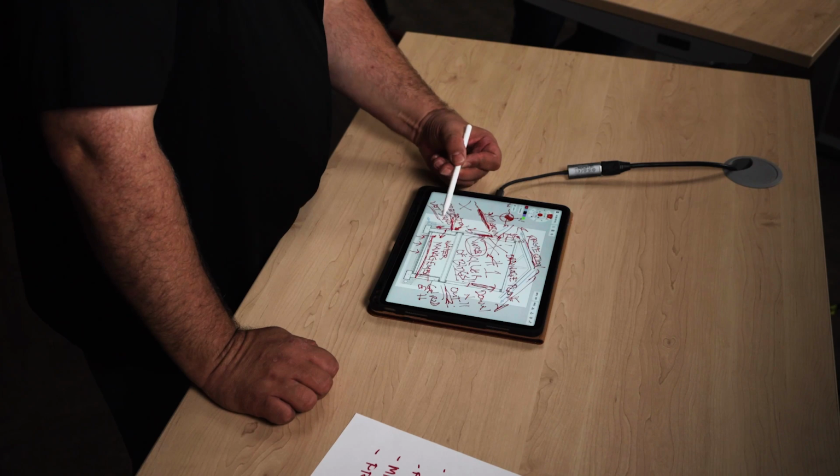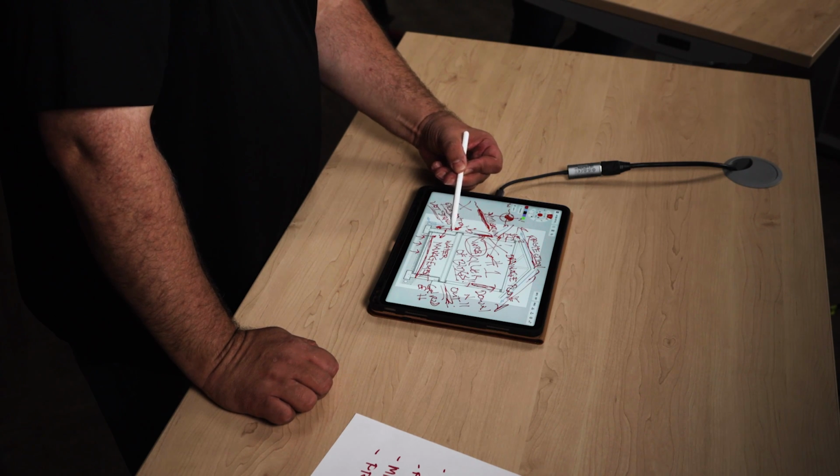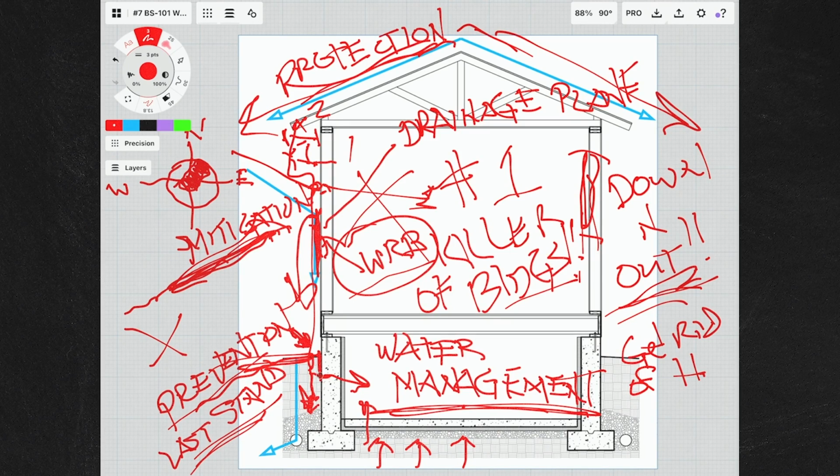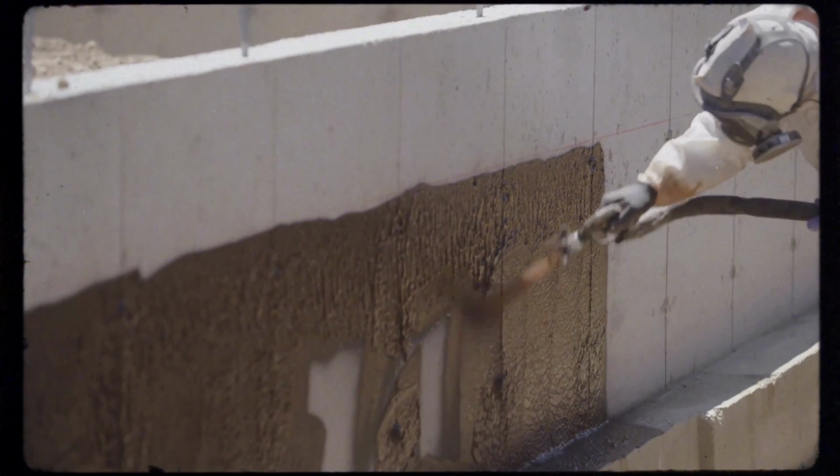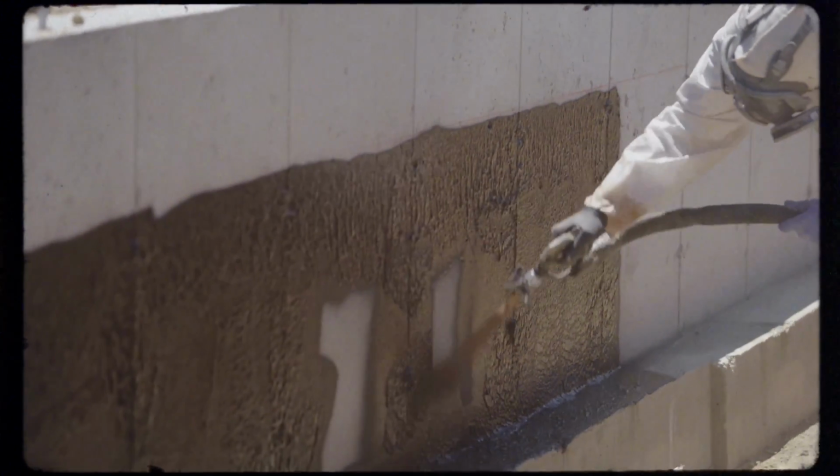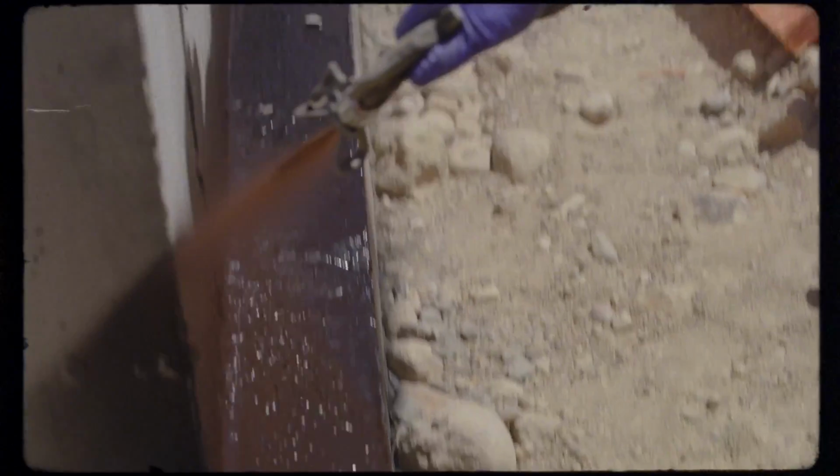Yeah. So one of the things that I always call out, and only because there are so many systems, I call out for a waterproofing, and it's usually somewhere in the 60 mil range. And when you put a waterproofing on there, that keeps the water out, but you have to maintain the integrity of the waterproofing.